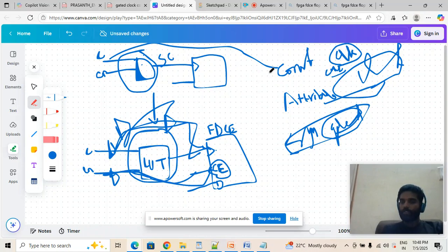There are some other scenarios we can see. This is one scenario I'm going to tell you. We can use some AND gates. More than one AND gate sometimes comes, right? In that case also the tool can understand and start mapping with the clock enable port, with the gating logic in the enable path, and the clock directly goes and connects to these flops. So this is another scenario, when I have multiple, slightly complicated logic on top of it. The tool will understand and start mapping it.